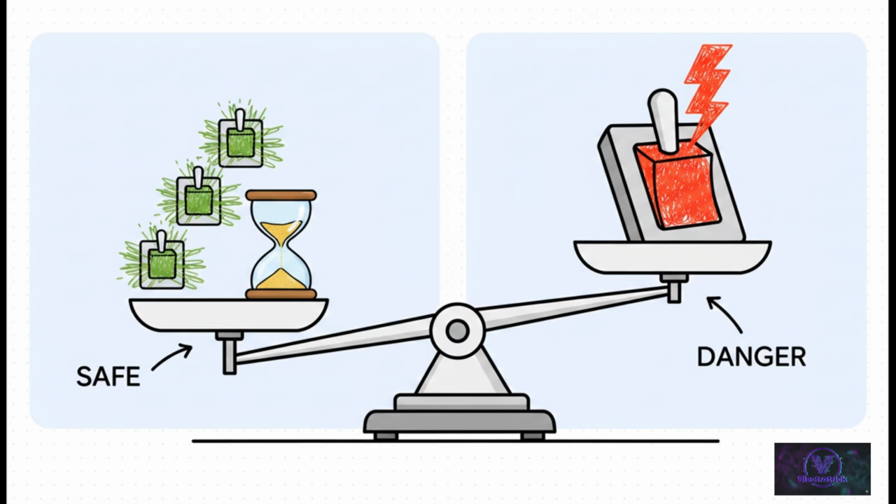On the other hand, if you just turn all the switches on together, your wake-up time is blazingly fast, but your inrush current is dangerously high and you risk crashing the system. It's the classic engineering dilemma. We have to strike a practical balance between performance and reliability.